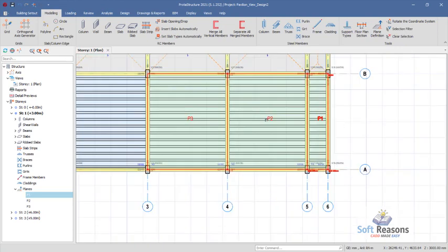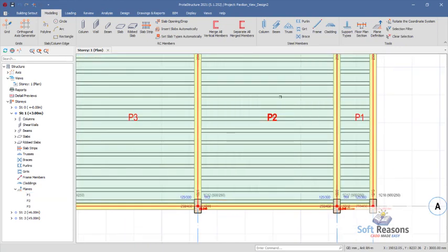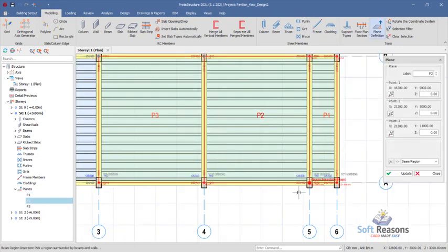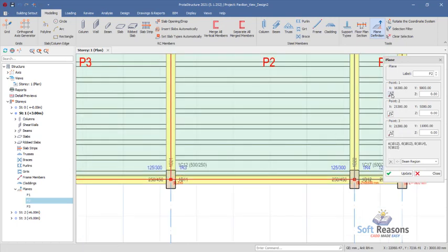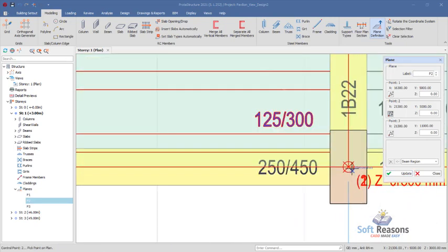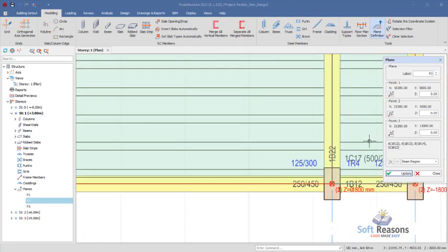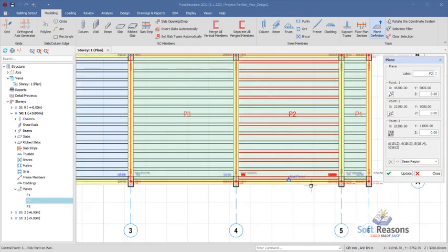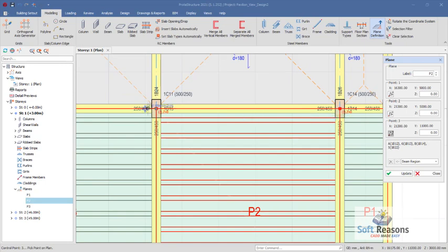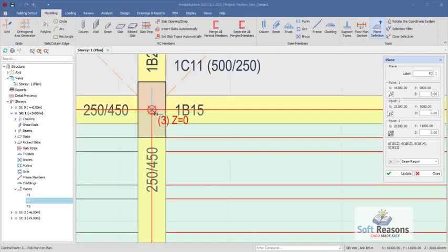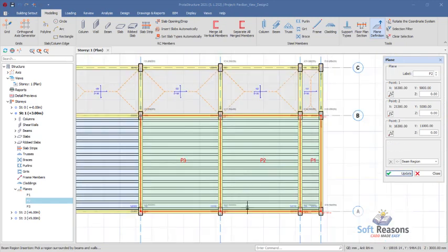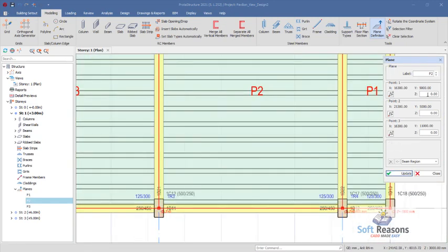So we navigate to P2 right there, select P2, right click on it, and then its properties, and then we need to set the points. Okay, we anchor here P1, update right there, anchor here to P2, and then zoom closely so you can pick the right intersection point. Okay, updated successfully, then P3 is going to be on a plane level. Okay, so we place that here, zoom closely to it, just like this, and then click on update right there.